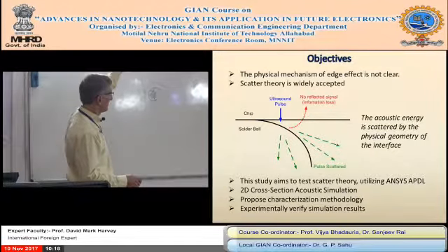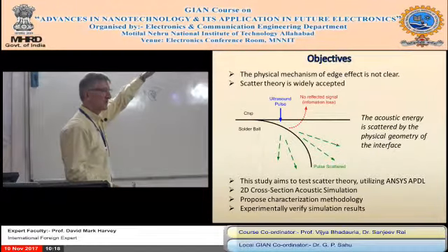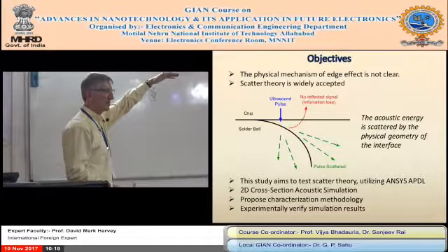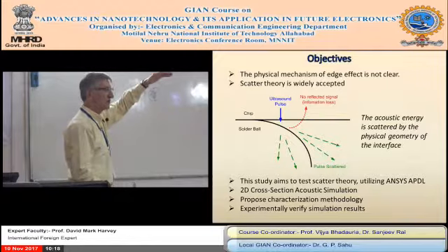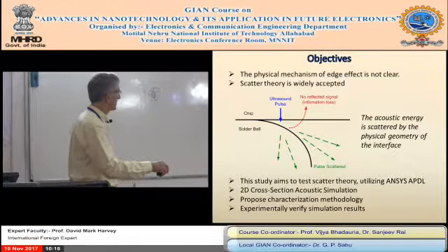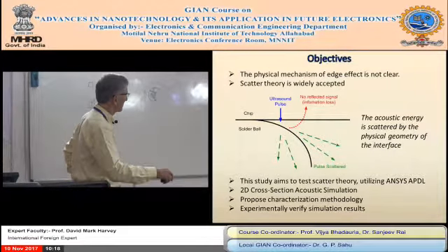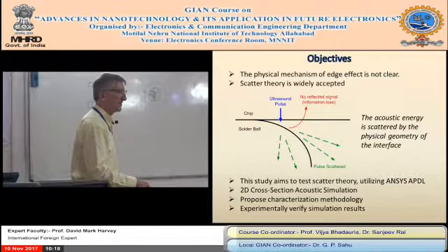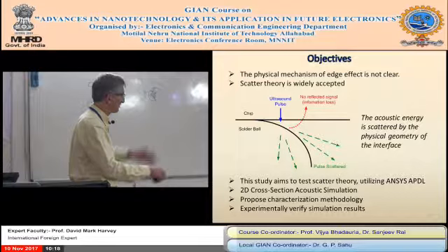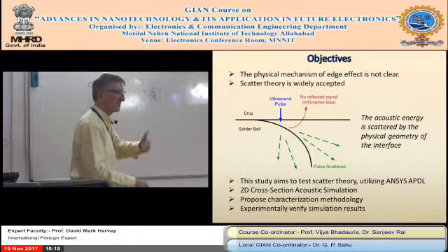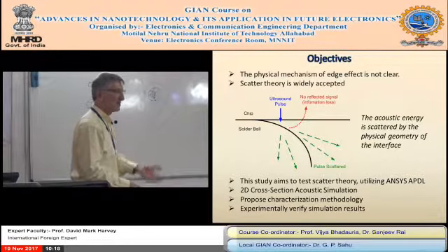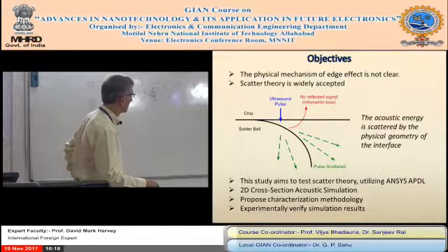He started out with a transducer up here, and he kept doing simulations, and even after 1 week he didn't get any answer. Then we realised, because the points are too big in this final map, we have to move the transducer closer down to the solder. So he made a virtual transducer, and then this gap is smaller, because every point there has to be simulated. There's a finite element step through. It takes millions of operations. So he set up this virtual transducer, tested that, and finally applied it to the solder bump.